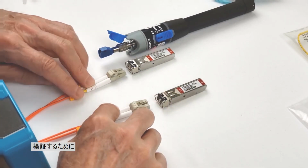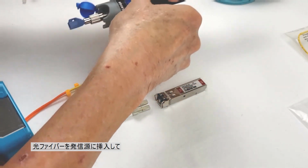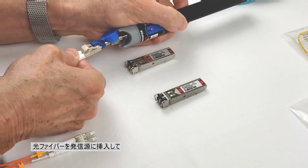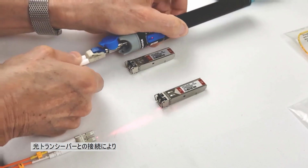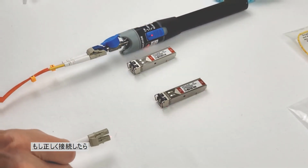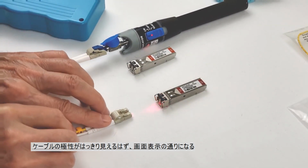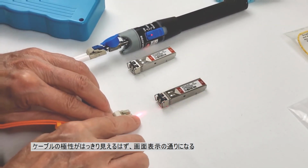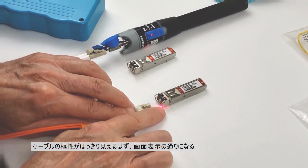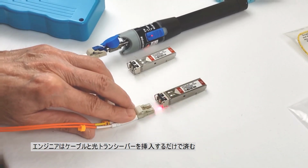To verify that this is correct, we're going to take the transmit side of the cable and plug it into a light source, which would normally be plugged into the transmit side of the optical transceiver. If the cable is correct, it should put it into the receive side of the next optical transceiver, and you can see it is in the right position or polarity. So a technician can just plug those cables in and it's going to work.